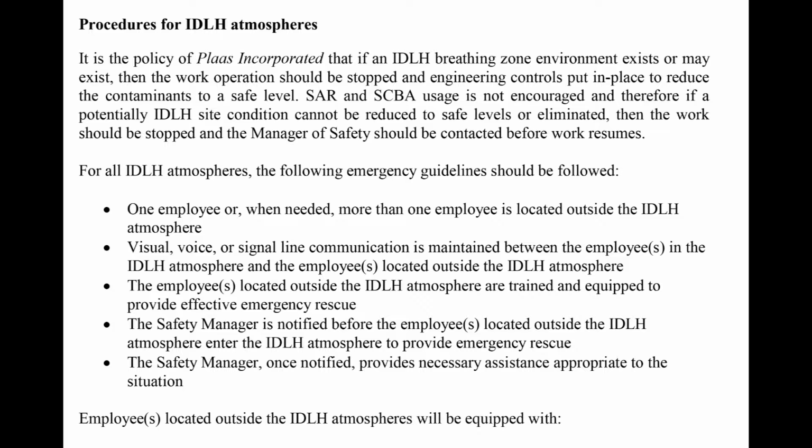For all IDLH atmospheres, the following emergency guidelines should be followed. One employee, or when needed more than one employee, is located outside the IDLH atmosphere. Visual, voice, or signal line communication is maintained between the employees in the IDLH atmosphere and the employees located outside the IDLH atmosphere. The employees located outside the IDLH atmosphere are trained and equipped to provide effective emergency rescue.